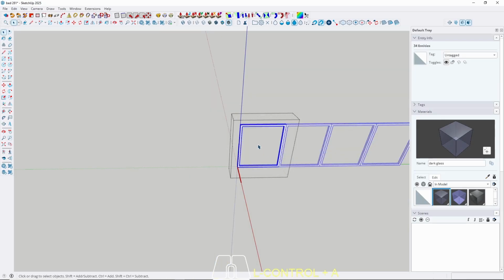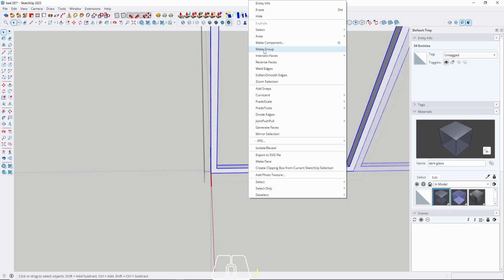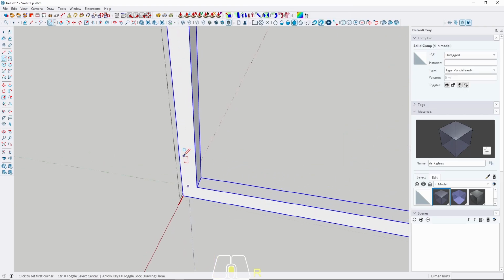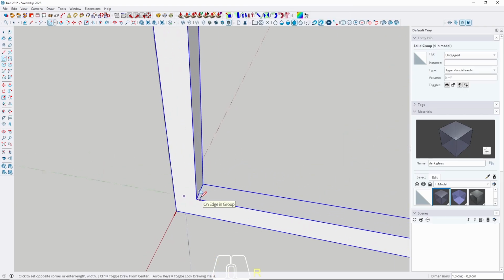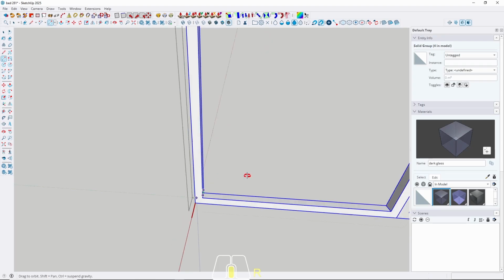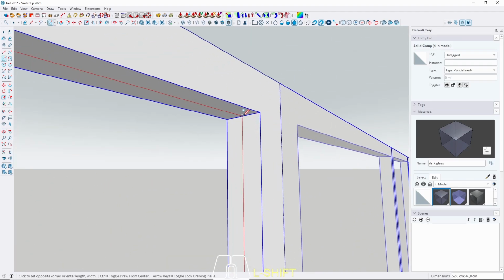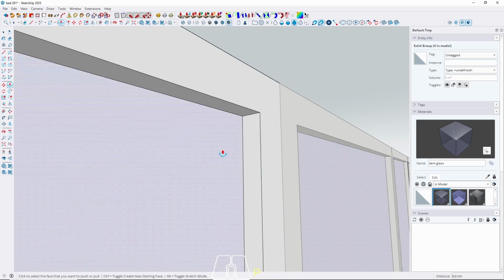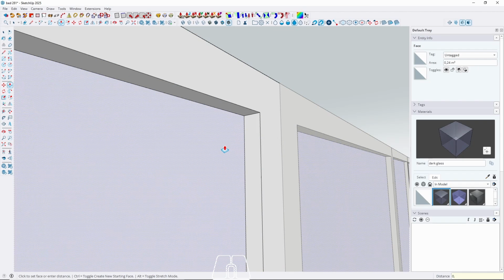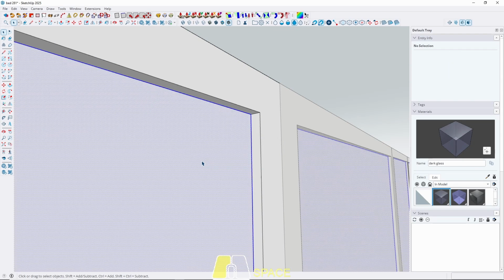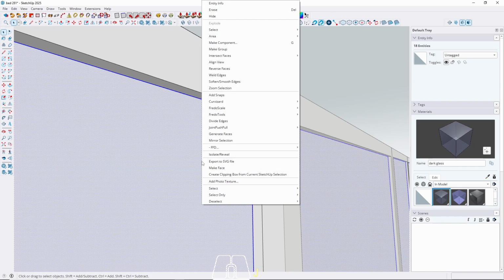And then next step just same as previous door. Make it group, and then give a glass, and make sure the glass has a thickness, because it's gonna affect the rendering result. So we have to do this. I know it's very lazy, but we have to get more realistic render.